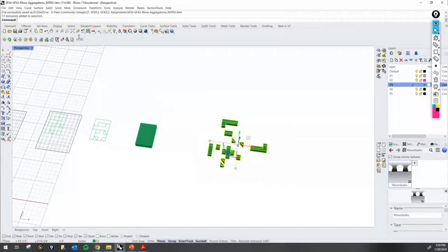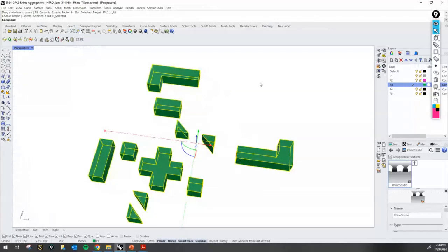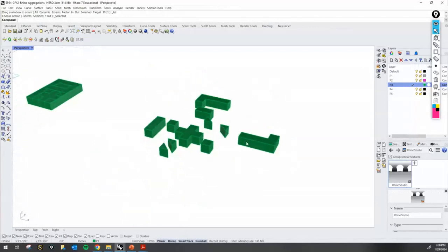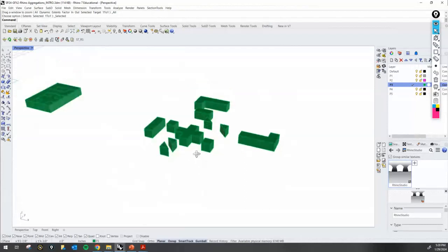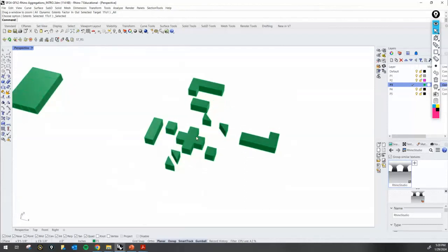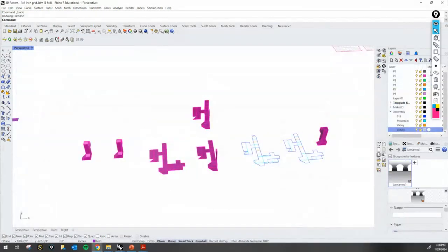Okay, class. So you should have ended again with something like this, which is all of your individual pieces extruded, and in this case, disassembled, right, from this assembled version. We're now going to look into a couple of things. We're going to learn how to join multiple little pieces. You see a join over here. How to join them using what's called Boolean Union. You see that that line is gone right there.